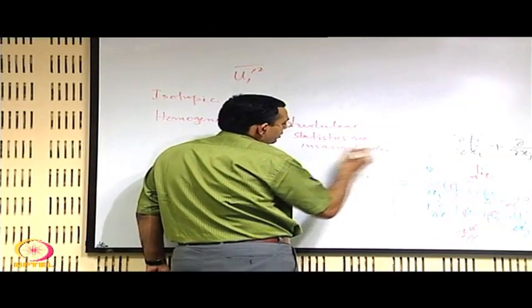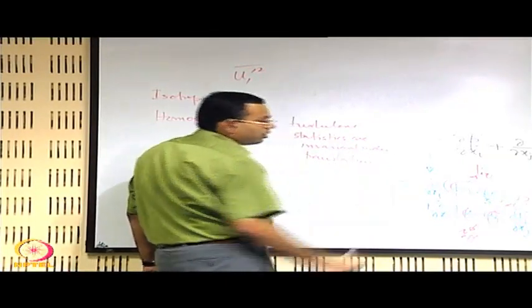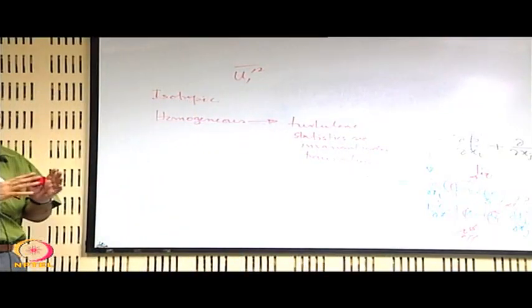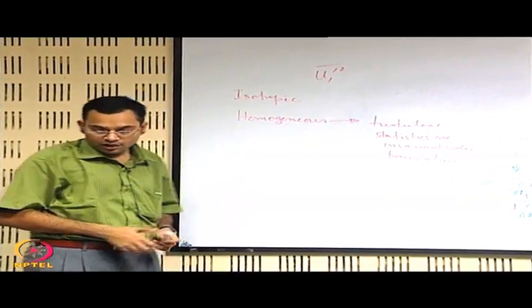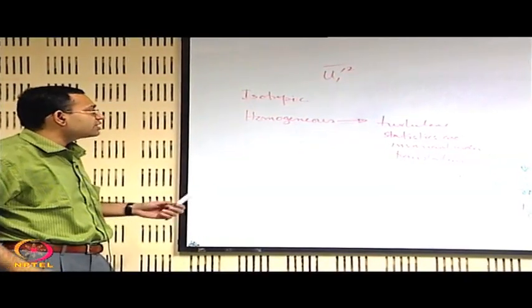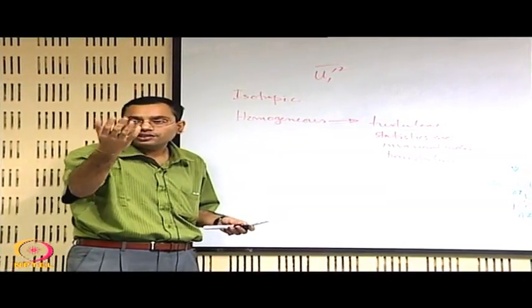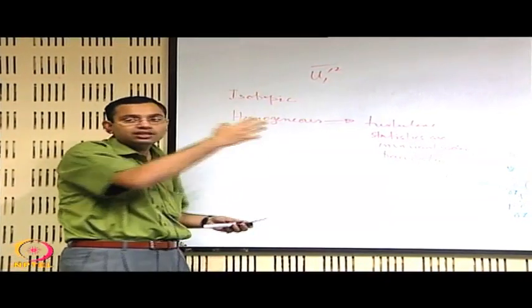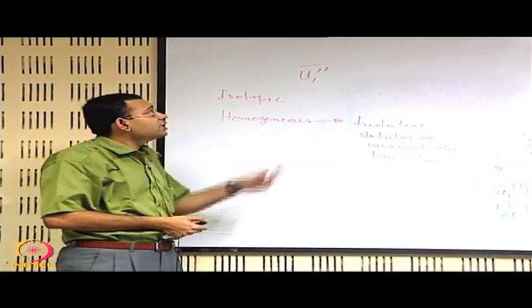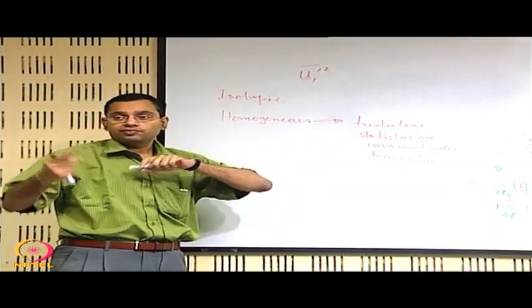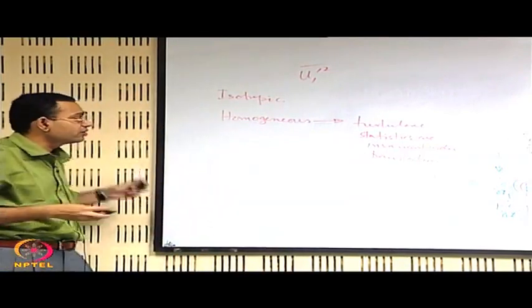When we say invariant under translation, the question is the translation of what? Obviously translation of the coordinate system by which the turbulence statistics are described. So when it is invariant under translation, that means no matter if you translate the coordinate axis to a different location and find out the same quantity in a statistically average sense, they are the same. It does not mean that u1 prime square is the same, it means the statistical average of u1 prime square is the same at all locations.